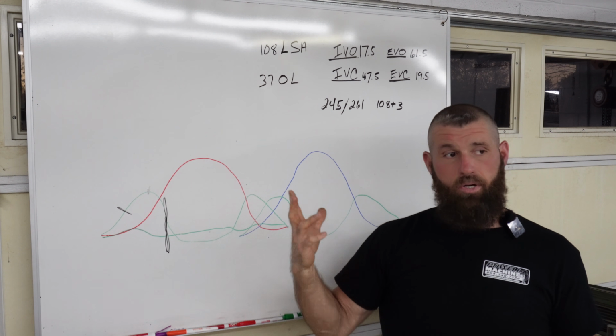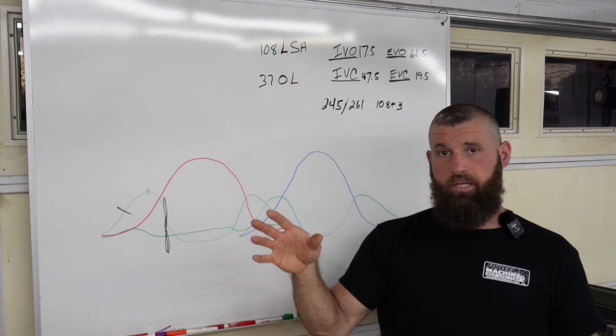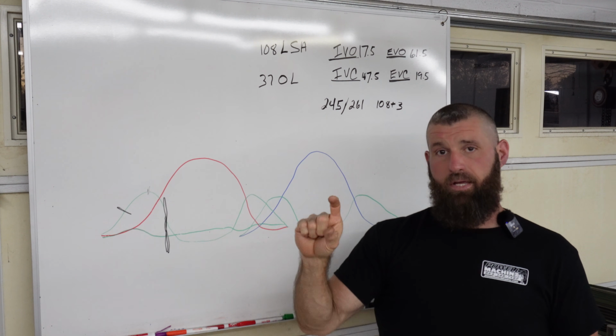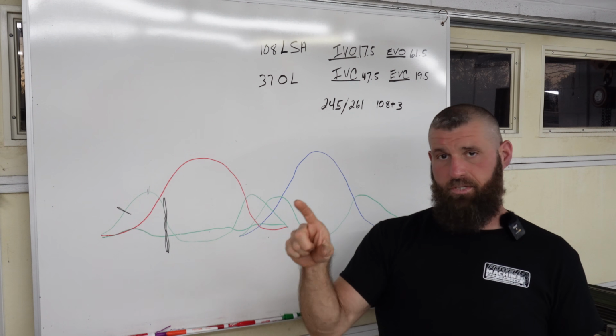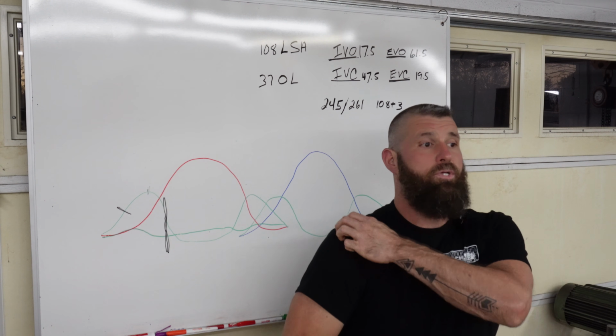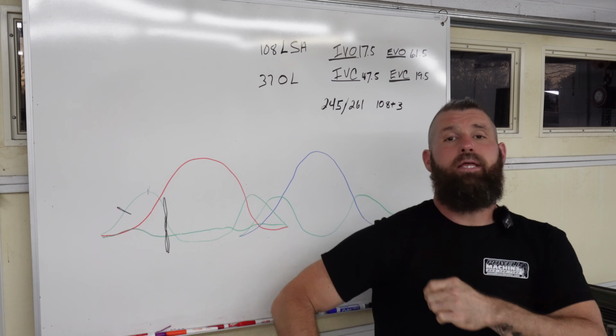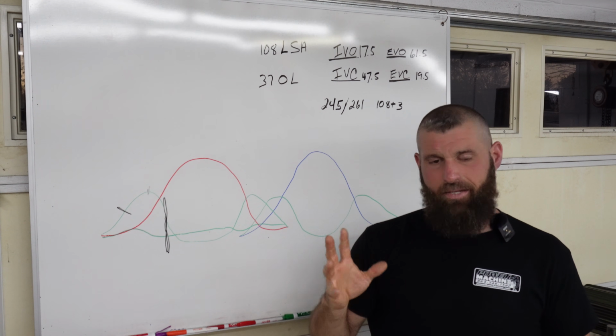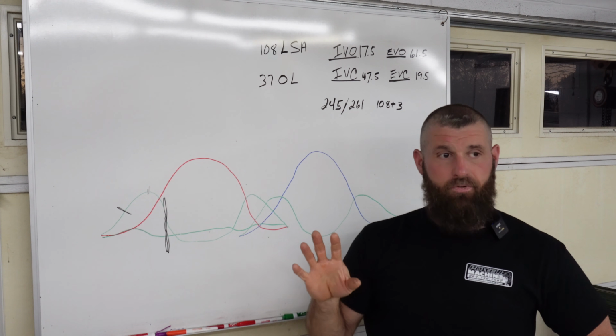If you've got a straight car and it's 600 lift, 600 is the number. I don't care if the head flows to 1.5 inches. If you can't open the valve but to 600, whatever that flow number is, that is the number we're going to use.